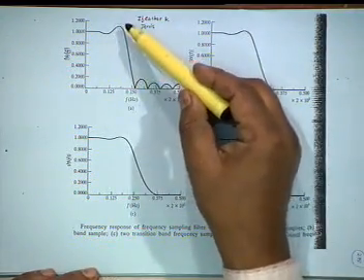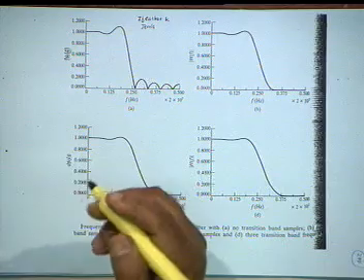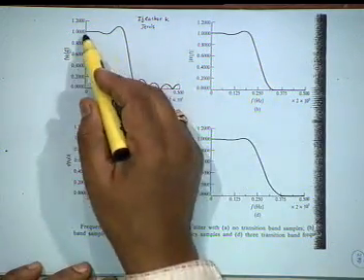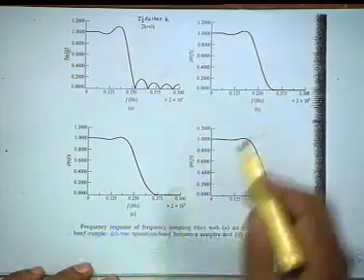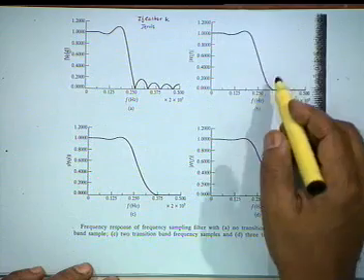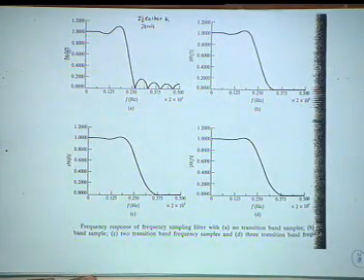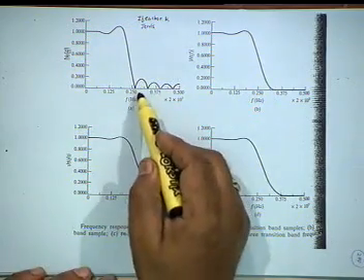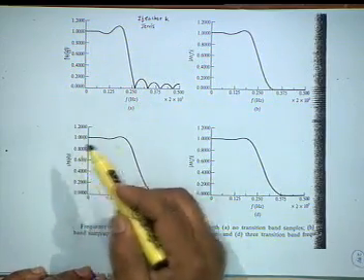This shows the frequency response without any sample in the transition, that is abrupt. And you notice that there is Gibbs phenomenon here, there is Gibbs phenomenon here. This is with one sample. Gibbs phenomenon has been considerably reduced, but at the cost of what? You see, the 0 occurs here at 0.26 or something.